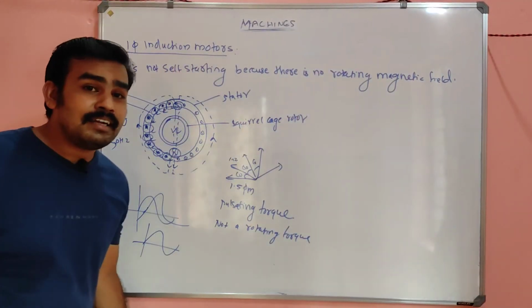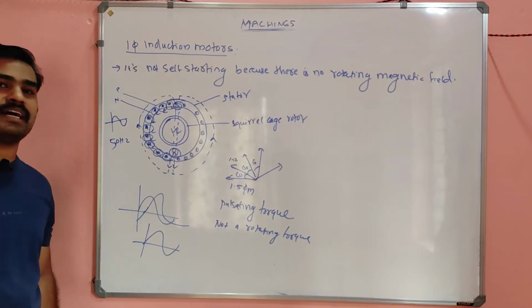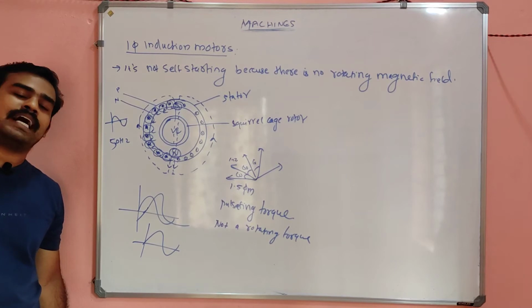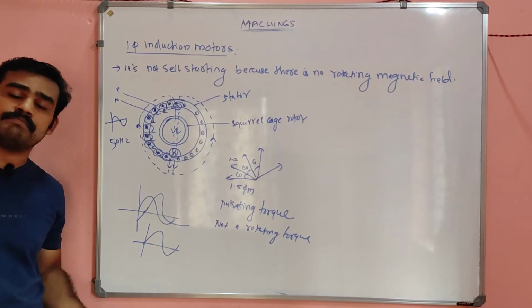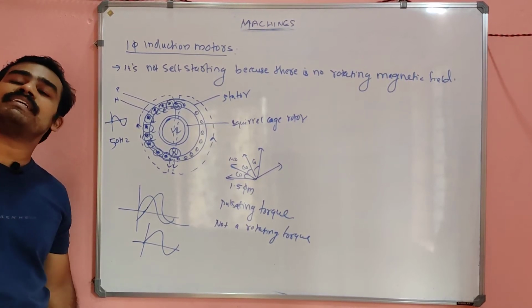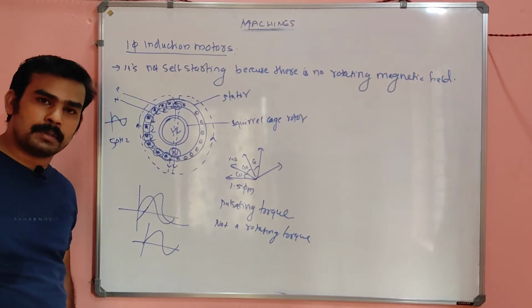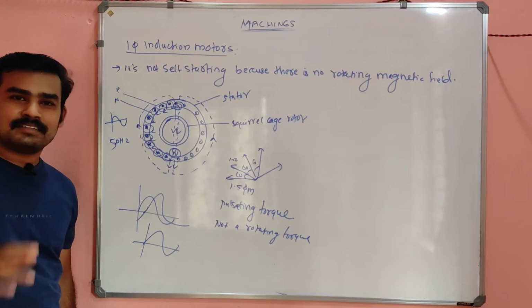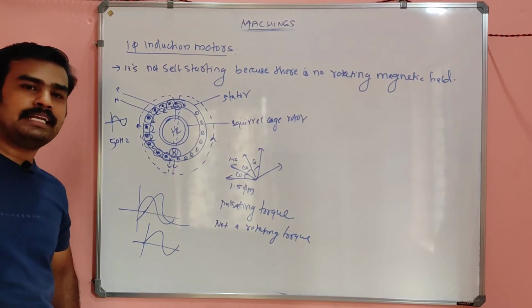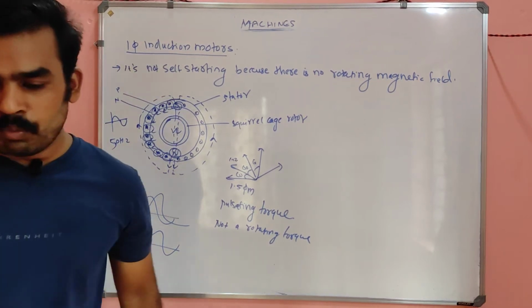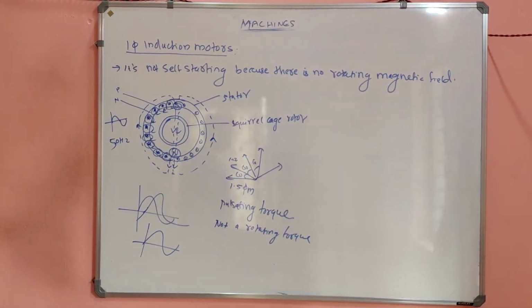So how can we start the induction motor? Anyhow, we have to start it now. Our fans and all, we are using single-phase induction motors. So we have to use single-phase induction motors in many situations. How can we start the single-phase induction motor? There you need a separate winding, which I will explain now. Did you get the idea why the single-phase induction motor is not self-starting, my dear?